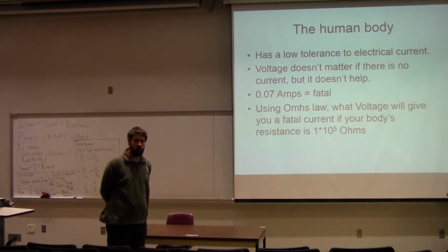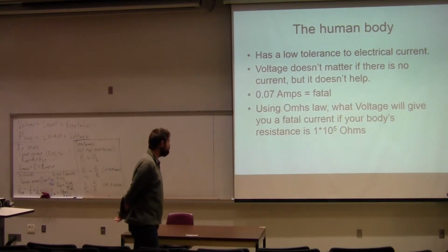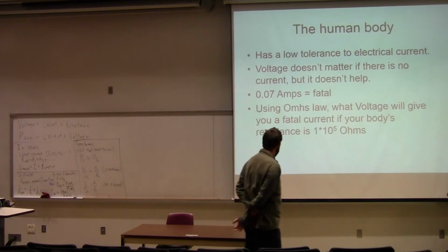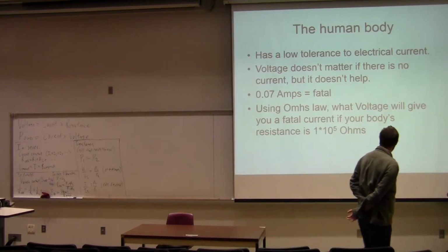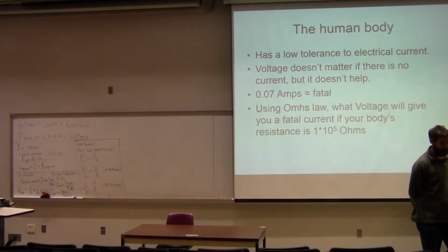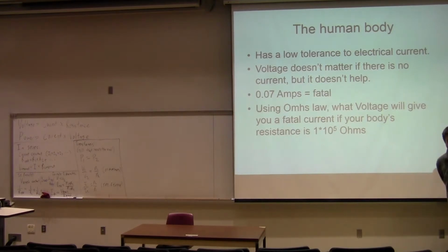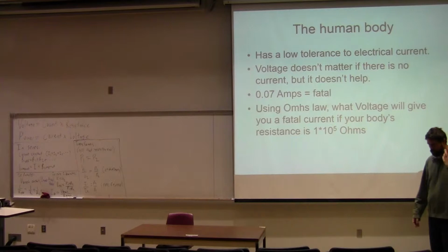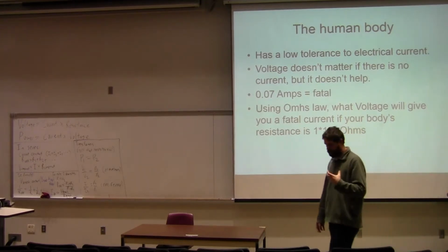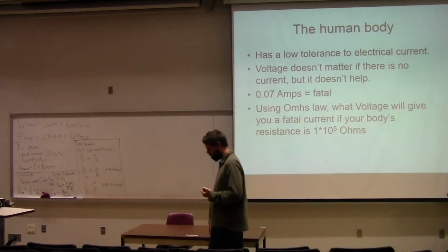So now let's use Ohm's law. How much voltage can I have if my body's resistance is 100,000 ohms, which is what it is on a dry day? So on a dry day, what will it take in terms of voltage to kill me?